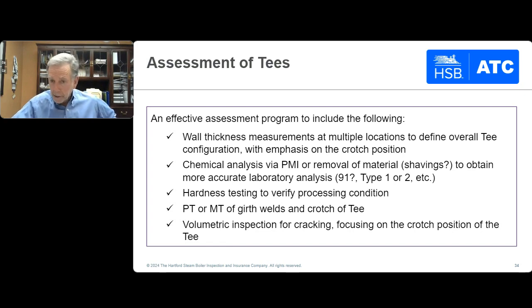In the case of the longitudinal cracking in the crotch position, at least for the ones that we've looked at, these clearly have started subsurface, and in those cases, volumetric inspection is going to be essential in order to determine, first of all, whether damage is present, and then using some of these advanced ultrasonic techniques in trying to come up with sizing for that damage as an indicator of the relative proximity of failure.